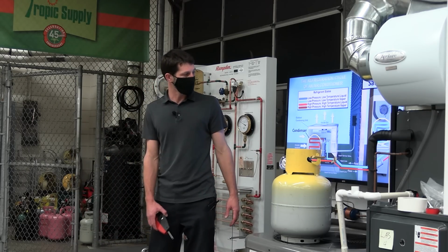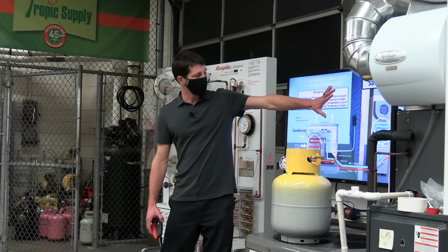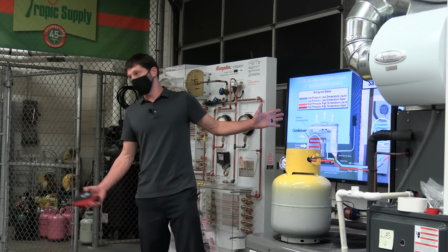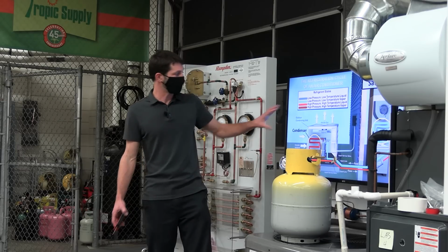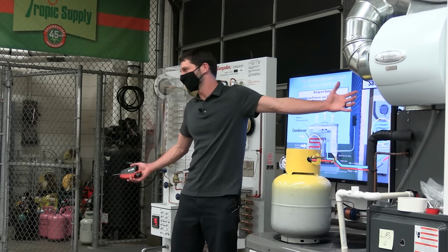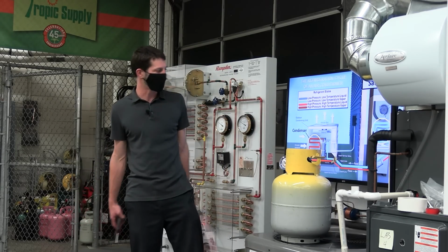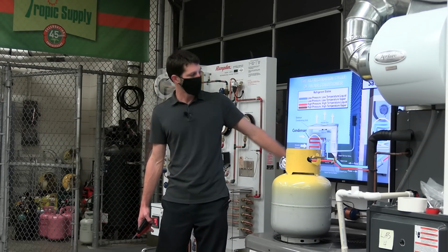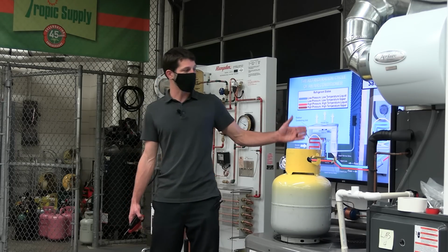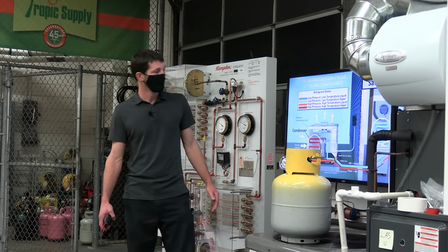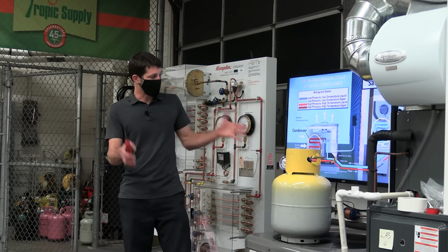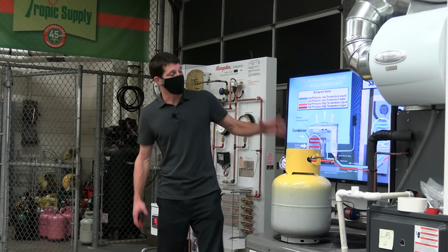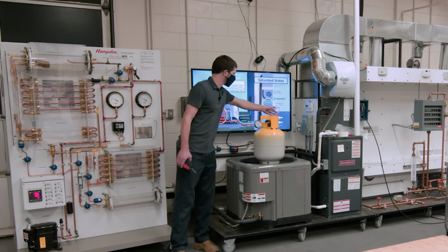So 70 degrees here. If this system was off, you'd have saturated refrigerant throughout this whole thing. And if it was 70, this is a perfect example, right? The 70 degrees outside and 70 degrees inside, that's rare for a split system, but just say it was, then you check the pressure on the ports, and it should convert to the saturated temperature of 70 degrees for R410A, and that just confirms that you have R410A in this system. So it's all saturated when it's off, unless you have a hard shut-off TXV.